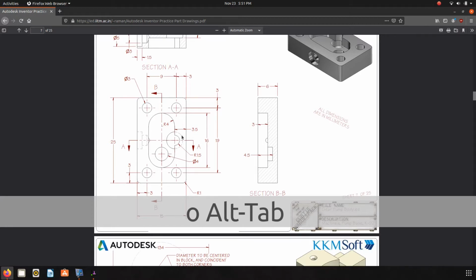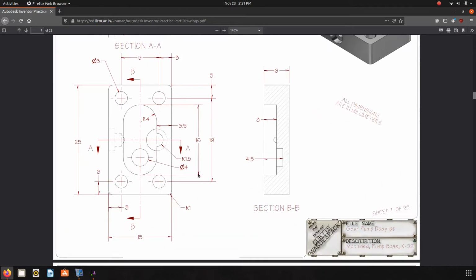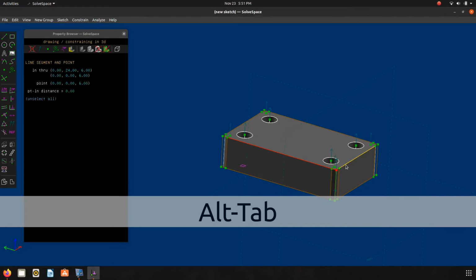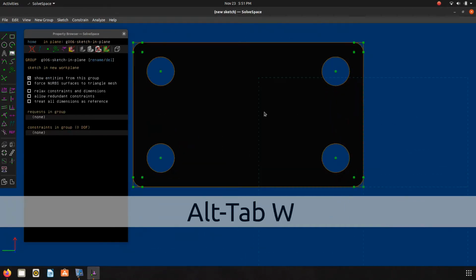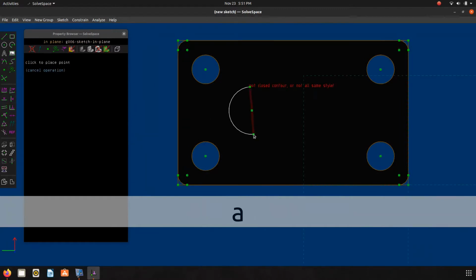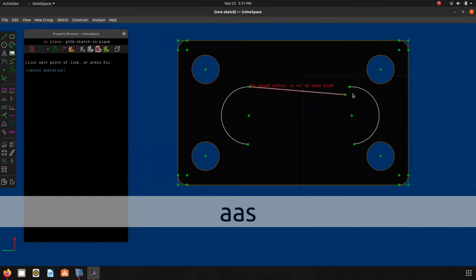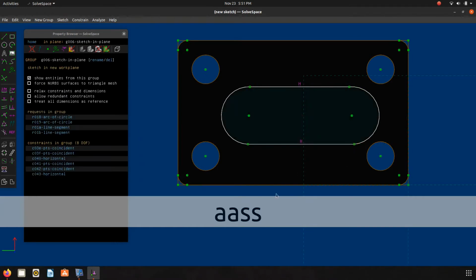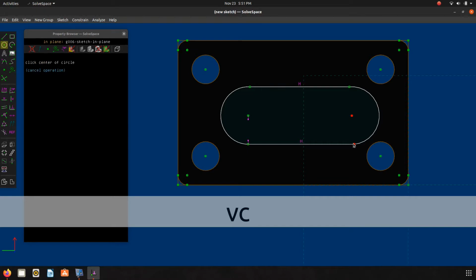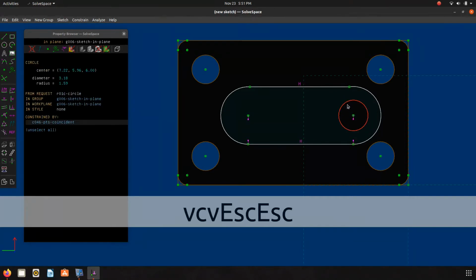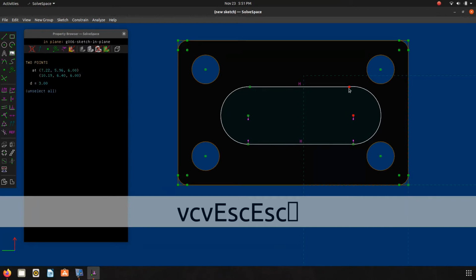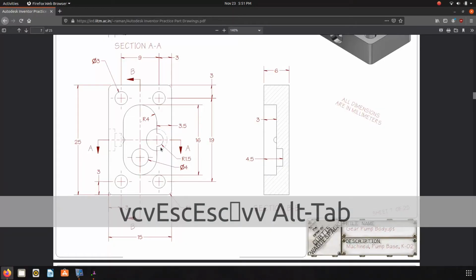we'll move in here. We'll make this shape here, which is 16 millimeters here, which is made by an arc, and 2 line segments. Okay, and we'll just put that in place real quick. Oops, that in place. Ooh, didn't want that. That, and that. Now that'll change in a minute here, but it's okay for getting started.